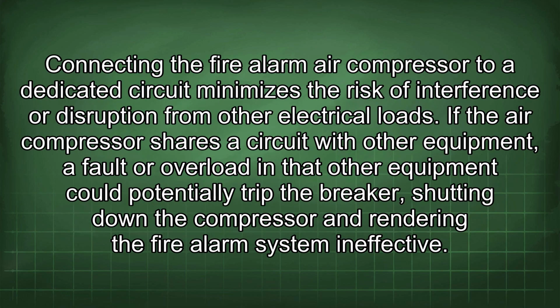Connecting the fire alarm air compressor to a dedicated circuit minimizes the risk of interference or disruption from other electrical loads. If the air compressor shares the circuit with other equipment, a fault or overload in that other equipment could potentially trip the breaker, shutting down the compressor and rendering the fire alarm system ineffective.